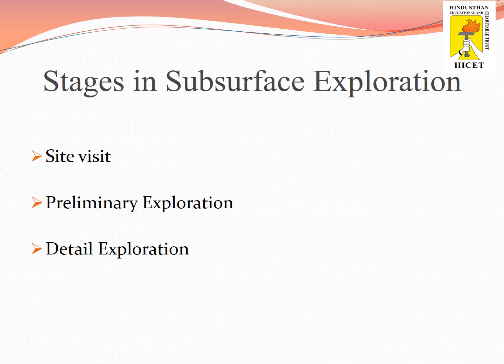So the next one is stages in the subsurface exploration. Generally, the subsurface exploration is carried out in 3 stages. First one is site visit, second one is preliminary exploration, third one is detailed exploration. In that, we are going to take up site visit as the first one.